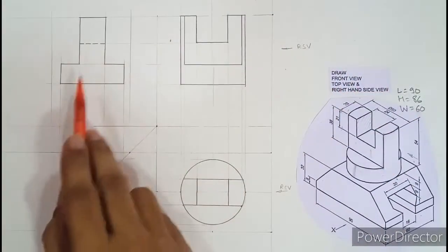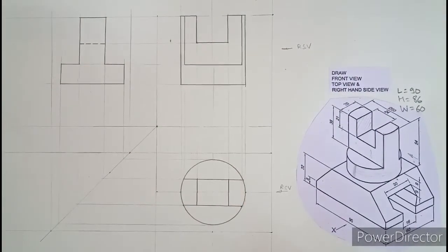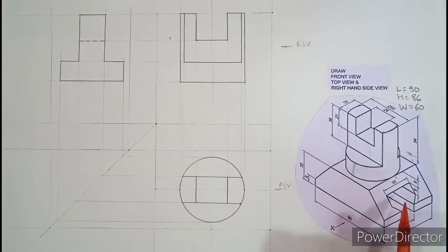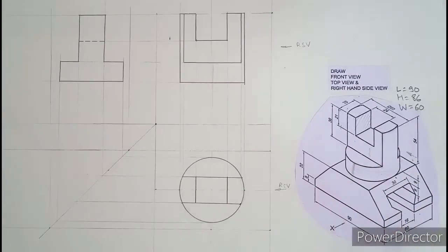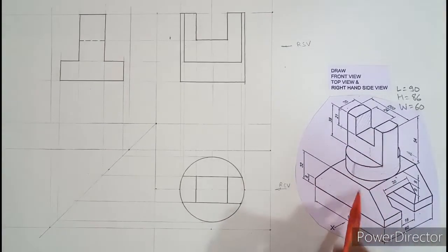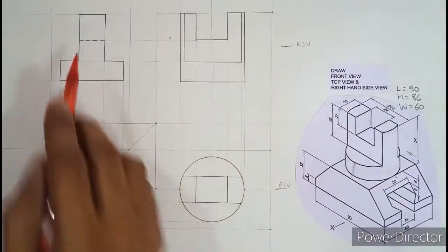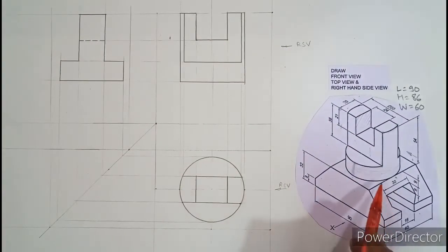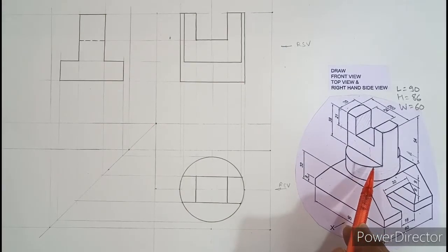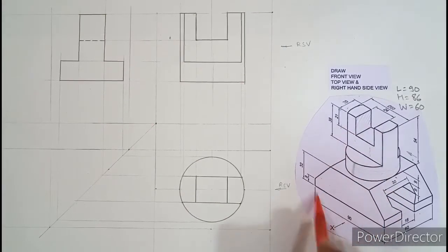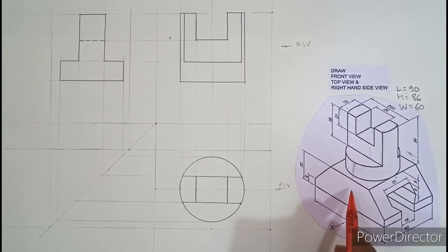So we have drawn the three views of the cylinder. This was what I was talking about. If you want to prepare orthographic, there is one more technique. We divide the object into 2 or 3 halves. So here we have divided into 2 halves. The upper half is a cylinder. So we have drawn 3 views of the cylinder, front view, top view, side view. Now we'll shift our focus from cylinder to the base or the platform. So we will draw 3 views of the platform. Okay, and by that you'll understand how the orthographic can be completed.